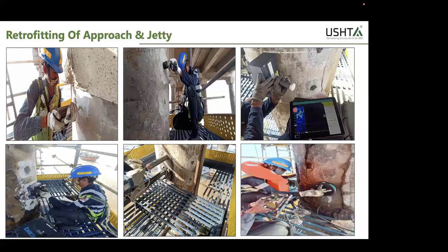This is the tomography test that we are conducting. It'll give you the exact location of voids inside the concrete, almost to a depth of 1.5 meters. Then this is the GPR machine, which will tell you the position of reinforcement cover, because in an offshore structure, what is more important is also the cover.